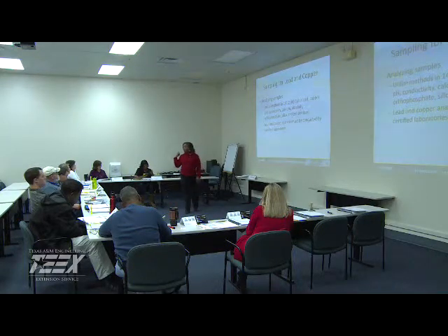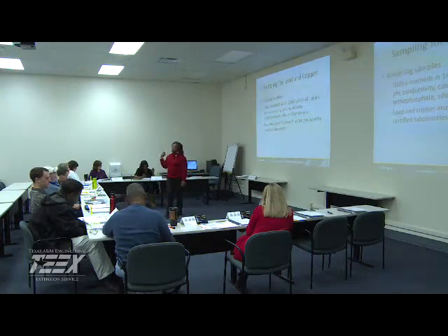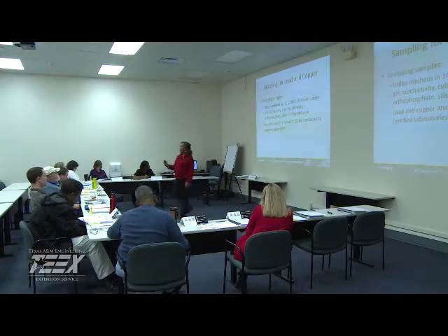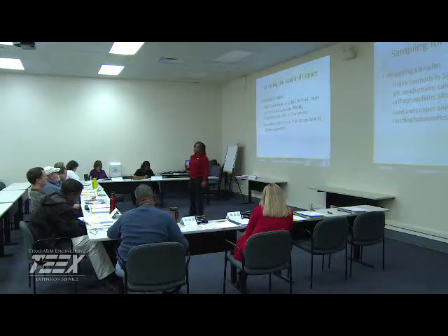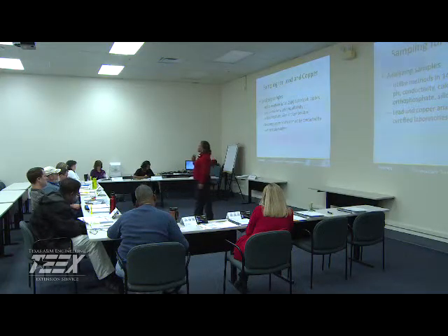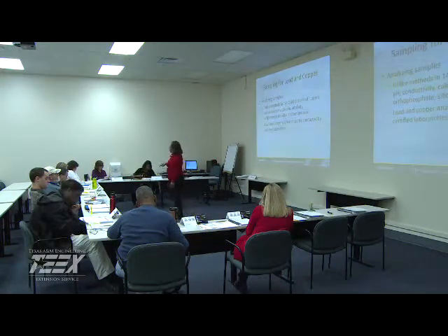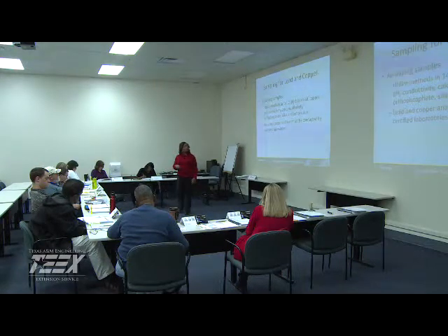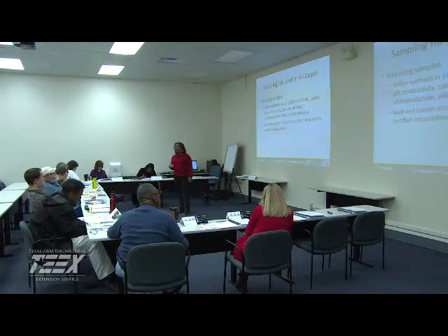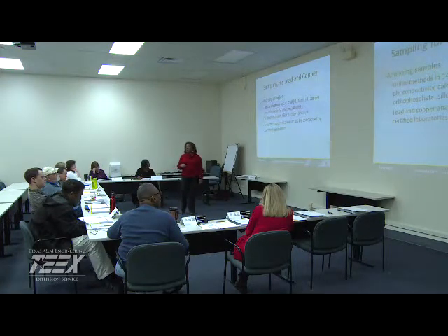We use the approved method to collect the sample. You have to use an approved method to run the analysis. Not every entity can run lead and copper. In order to run lead and copper, it must be an approved, certified laboratory. Generally, your state will have its own laboratory running, or a lab that's NELAC certified, but it must be a certified lab to run the lead and copper. Any other laboratory can run these other water quality parameters as long as they are using approved methods.